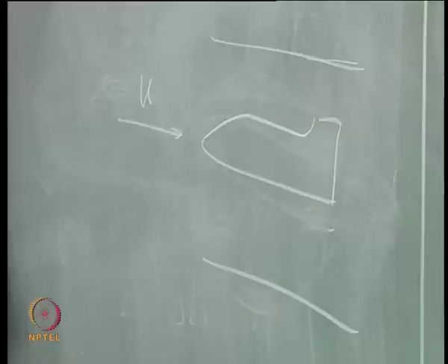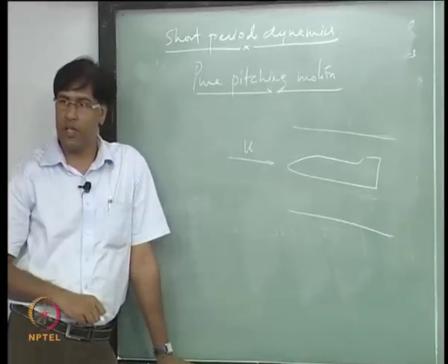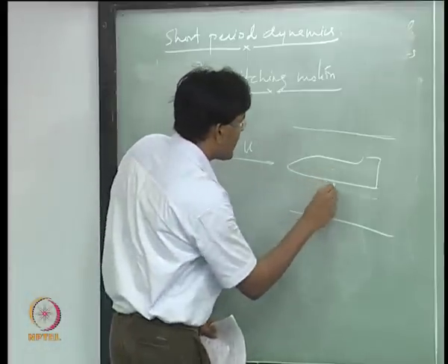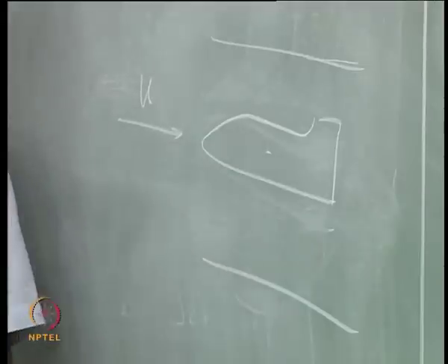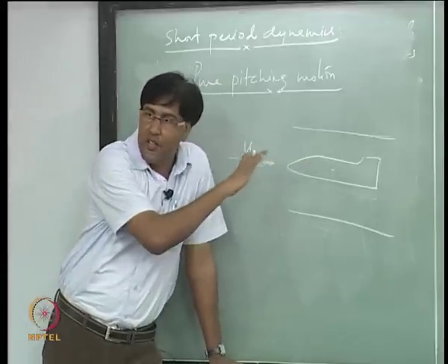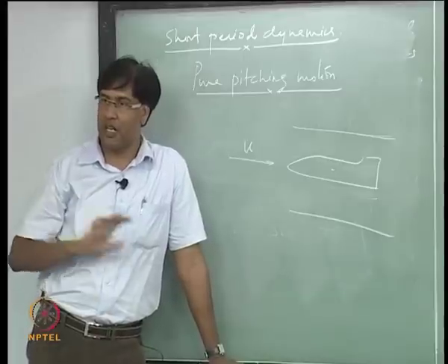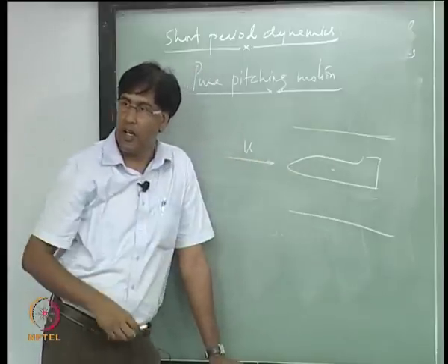So, you are flying at cruise, alpha is 0, and then you give a perturbation in pitch. So, you have motion around this point through which we have passed the rod in the wind tunnel. The aircraft will start pitching about this; it is constrained to only have pitching motion and nothing else. You cannot have a forward speed or any other motion.